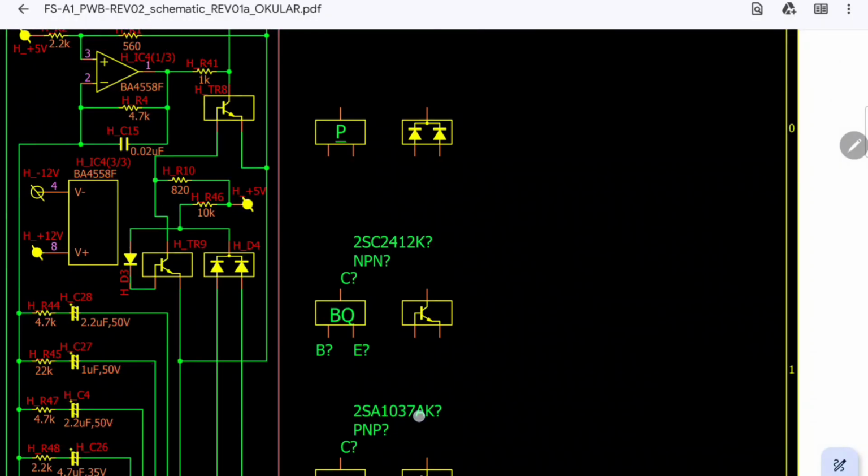For each of the inputs, we have a current that goes through its resistor, different resistors and different currents for V1, V2, V3, and V4. We know that here we have 1 volt, and because of the way the op-amp works, we have also 1 volt in here. So all these currents are summed and go to here, and here we have a very high impedance, so the sum of these currents will go through this resistor and this gap.